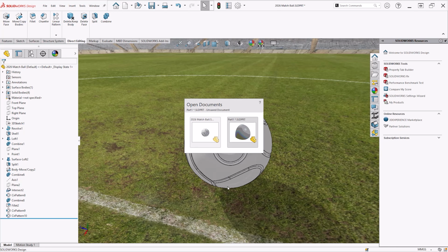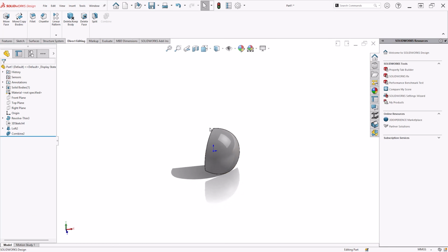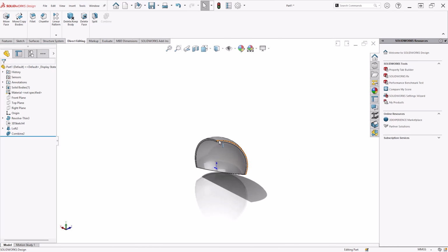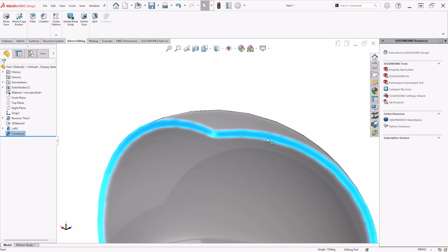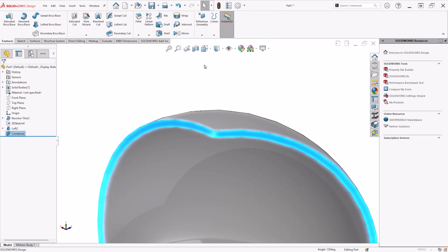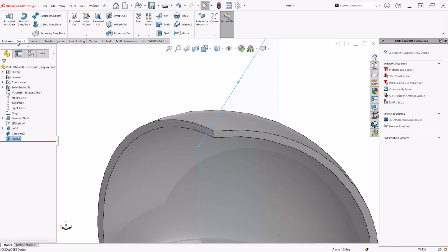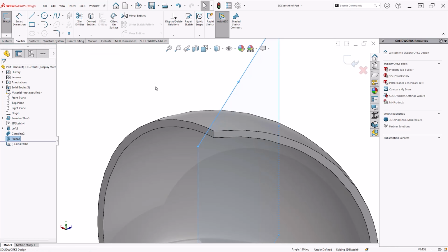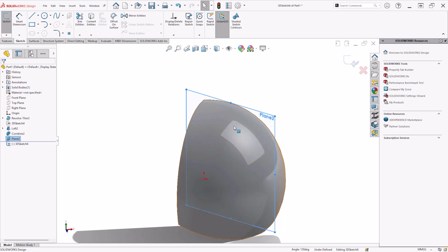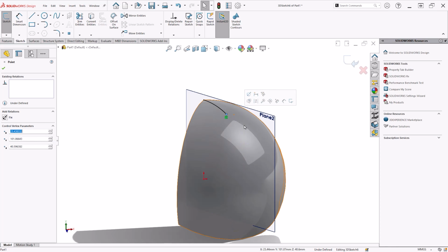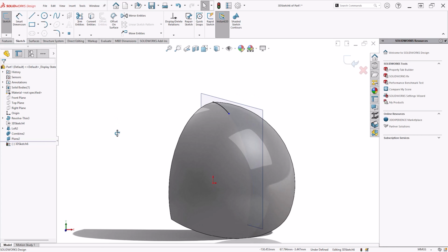I'm going to try and see if I can draw just half of that S. It needs to go into the mid edge here, but it starts off along this upper surface. To help me, I am going to create a quick reference plane, and we need another 3D sketch. Why did I create the plane? Well, if I have the plane selected and this face, I can create an intersection curve. It plots on that surface this arc here, which shows me exactly where that next piece will sit.